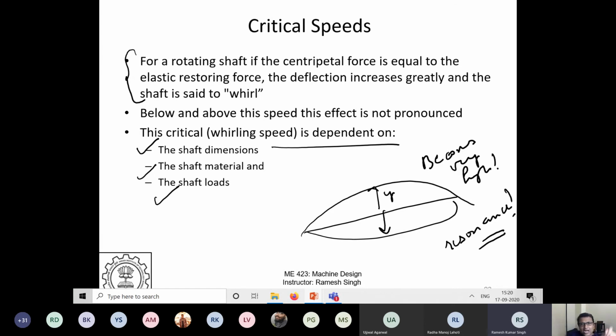So when they start, they go very fast. They pass the first natural frequency very fast so that it doesn't really dwell there. If they dwell a little bit, then the shaft will start to vibrate very vehemently. So they just ramp it very fast across that natural frequency. But for that, you need to know that, right? If you don't know, then you will damage your shaft. So for a lot of these rotary equipments, knowledge of rotor dynamics is very, very critical. Otherwise, you will end up destroying millions of dollars of equipment.